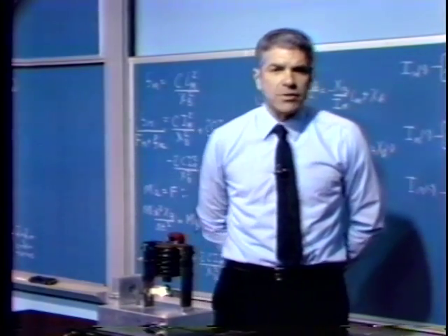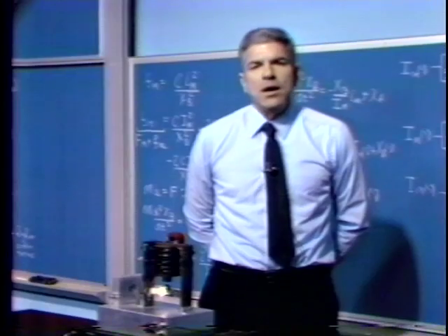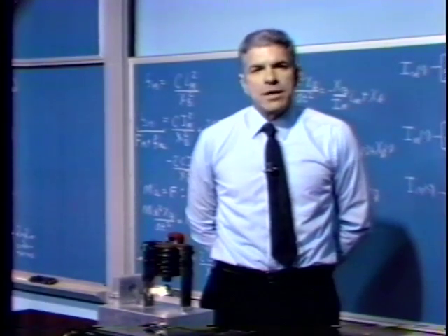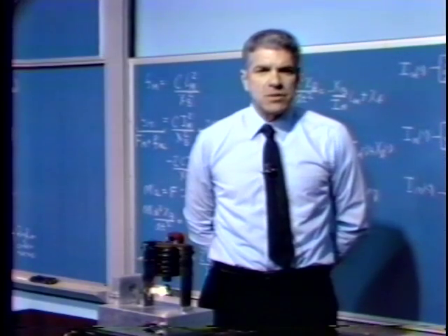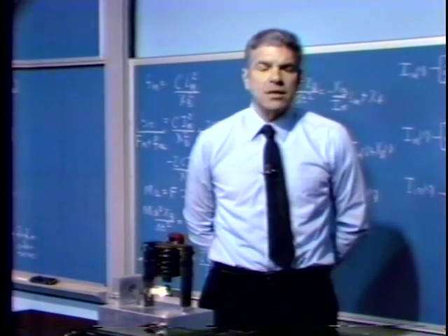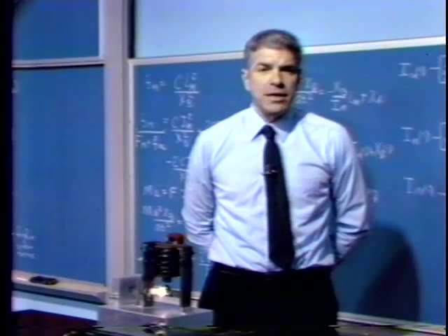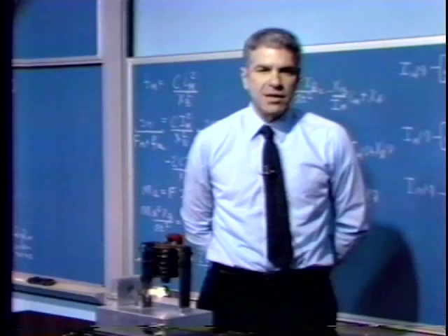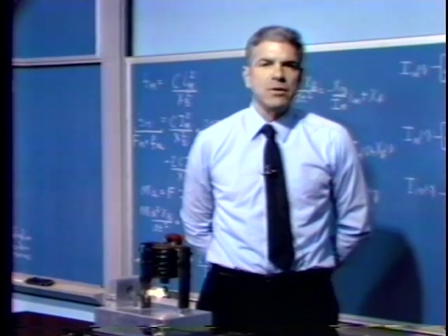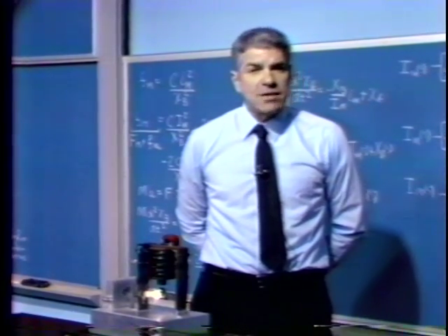We can, with the linearized analysis we've gone through, readily identify why the system should be unstable on an open loop basis, if you will. The dynamics associated with the ball and the magnet have a pole in the right half plane, and we certainly anticipate then unstable behavior unless we do something to counter that right half plane pole. So we've seen that behavior.